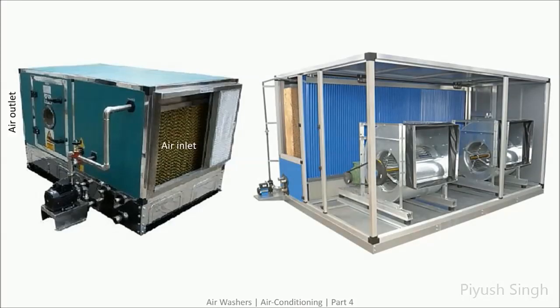The incoming air is filtered to remove pollutants using an air filter. The filtered air is then made to flow through a spray of water, and during this flow, air may be cooled or heated, humidified or dehumidified, or simply adiabatically saturated, depending on the mean surface temperature of water. The flow of water is maintained by a water pump. The sprayed water gets collected in the water tank at the bottom of the enclosure. The water level in the sump is maintained at the required level by supplying water lost in case of humidification.